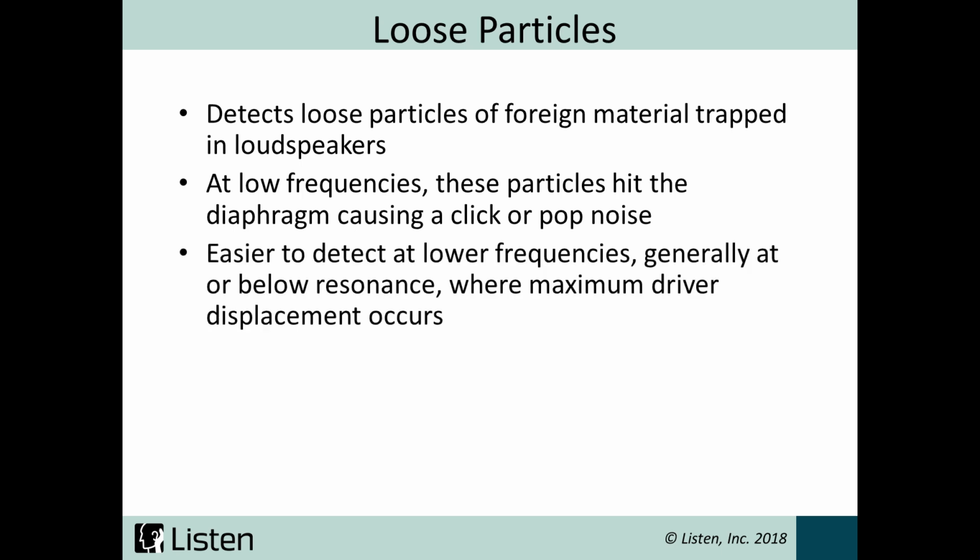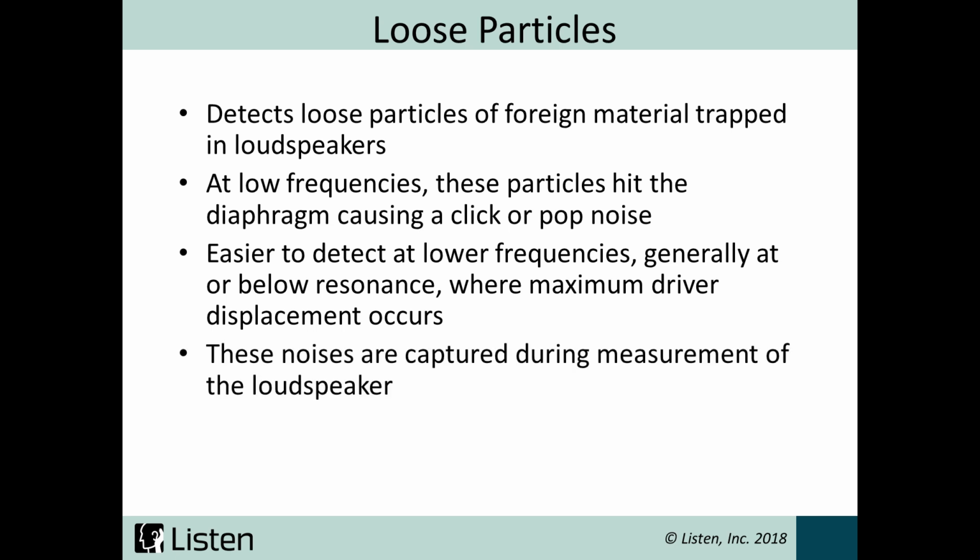These defects are easier to catch at low frequencies, usually below resonance, where maximum driver displacement occurs. This algorithm can detect those loose particles as impulses in the sound emitted by a loudspeaker during a measurement. Loose particles is also useful for detecting digital artifacts like squelches or dropouts. Loose particles is available in all algorithms.